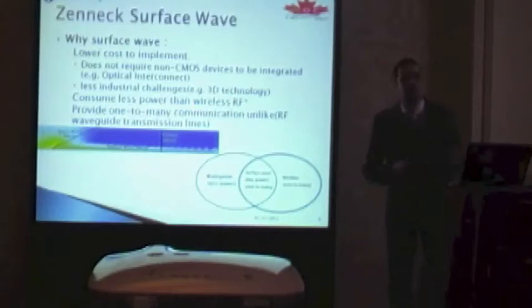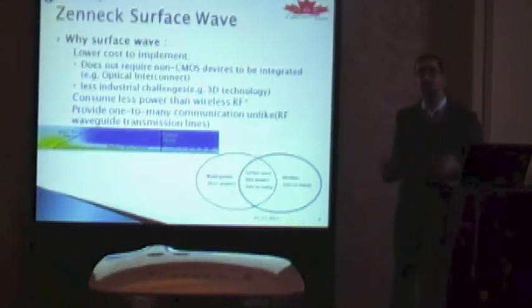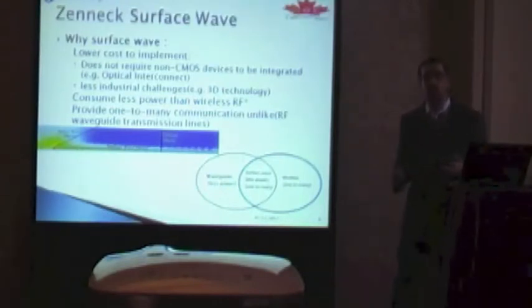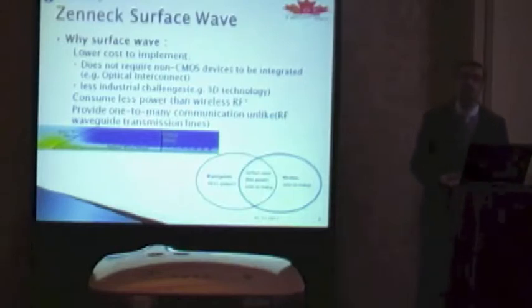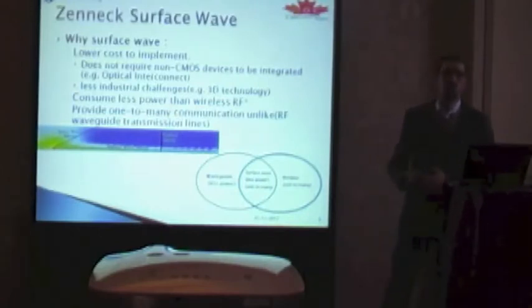In general, radio frequency interconnect has a lower implementation cost because it doesn't need non-CMOS technology to be integrated inside or outside the chip, such as optical interconnect, sorry, and doesn't face that many industrial challenges such as for 3D, such as heat, and so on. So radio frequency interconnect can be classified into two types.